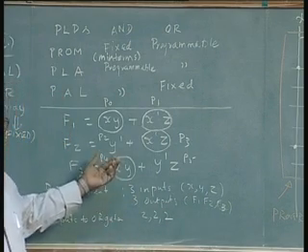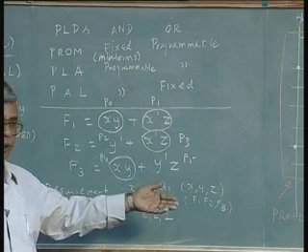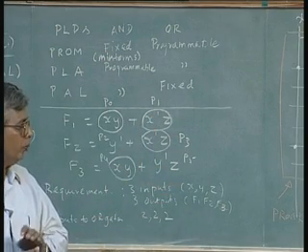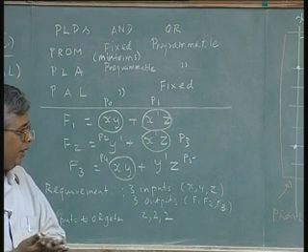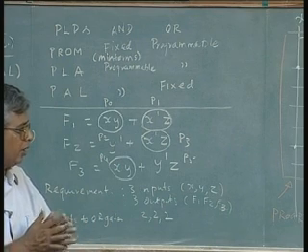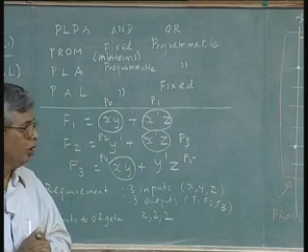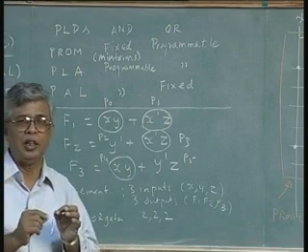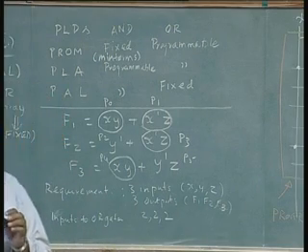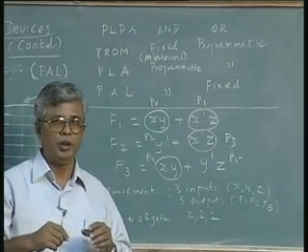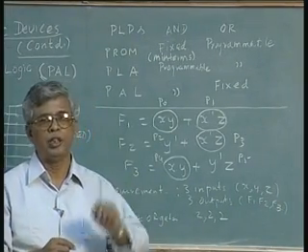Here we have to reduce the total number of product terms going into each of the inputs, so that the OR gate can be used. Even though it is less flexible, consider design effort and the number of inputs. In the earlier case, I should be able to connect each product term to each OR gate.